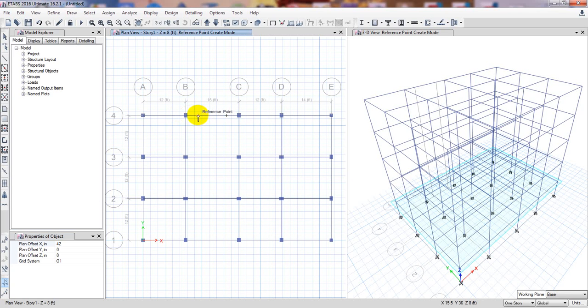So when it's done, now we need a slab here, and its size will be 3.5 feet, okay. That means 7 feet. This is in the y direction and minus y direction actually. So I'll just copy that, Ctrl X, I'll give the data here, Ctrl V, and it will be minus y. So if I take a point here and another point here, okay, and also one point here and another point here.